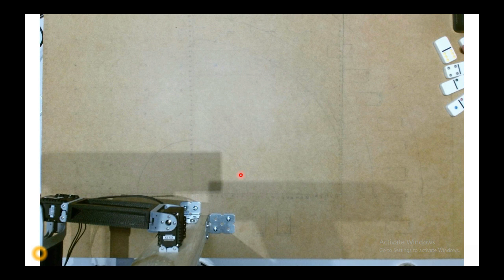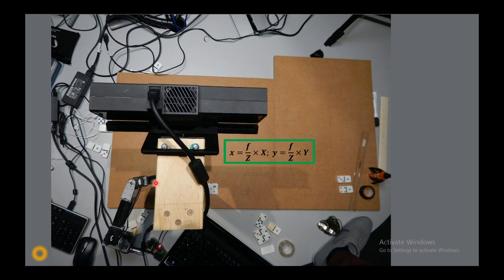For the project, the sensor position was chosen such that the camera looked down directly onto the workspace, resembling an orthographic top view of it. This was done to reduce the complexity of a 3D workspace to a 2D one. This setup allowed us to perform coordinate transformation using the focal length to depth ratio and doing vector addition to establish the origin position. In addition, Kinect 2 was selected due to its high resolution with respect to the other options.